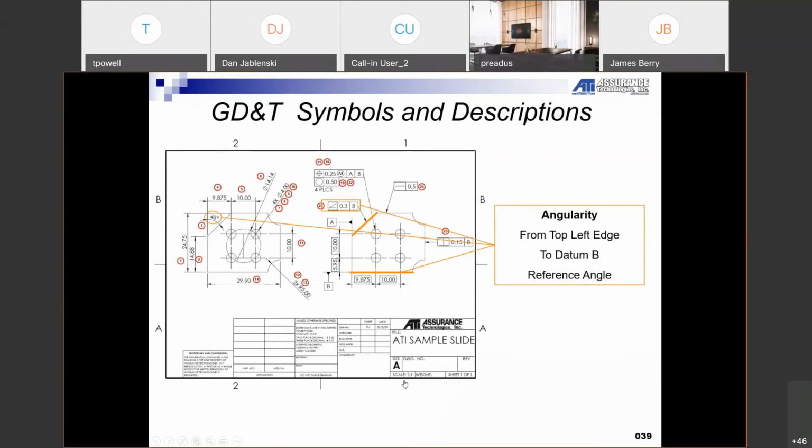Again, like I was talking about the battle planning, you really want to, before even measuring the part, look at your print, what the GD&T is asking for, what basic dimensions it's meeting, and make sure that it's all there. There's times that I've seen true position callouts, which we'll get to in a little while, that don't have the basic dimensions too. They got left off the print. So then we get to go talk to engineering, find out what it is. If you have the CAD file available, we're able to help you out there too. So before even measuring the part, make sure that when you're looking at the GD&T symbols and the callouts that you have all the dimensions that you need.